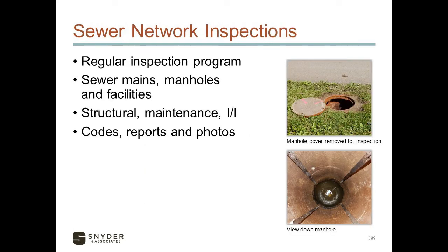A lot of communities have a regular sewer network inspection program in place, which is great. What are we trying to do? We're trying to inspect our sewer mains, our manholes, and pump station gate facilities to establish any structural maintenance and I&I defects that we have. We're doing that through various system codes that identify defects, reporting methods, and then photo documentation.